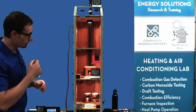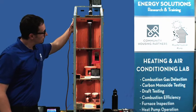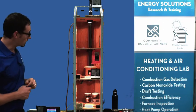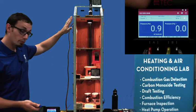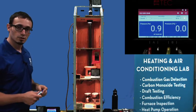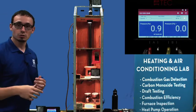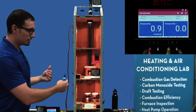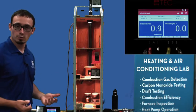The first one I want to do is seal up the attic. If I seal up the attic bypasses, what's happening to my pressure? If I look on my channel A, my pressure at the top of the building, 0.8, 0.9, and then down there at the bottom, it's 0. So really all that's showing me is that the range of pressure is the same, and the range of pressure is really just dictated by the height of the building and the temperature difference between inside and outside. If I didn't have any temperature difference between inside and outside, I wouldn't have any buildup of pressure.